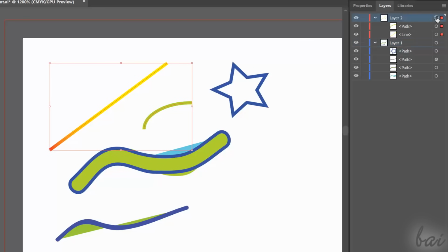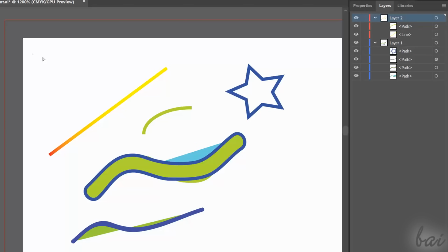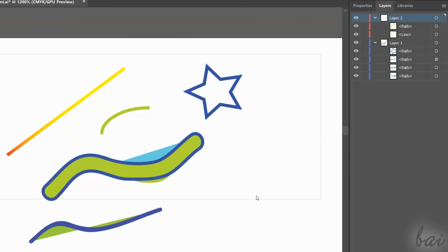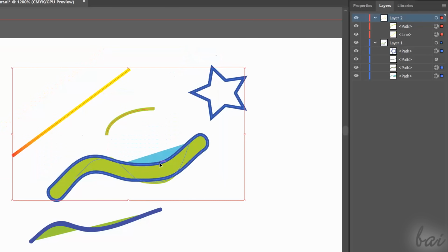You can select a whole layer from the Layers window, or select multiple objects by holding Ctrl down and clicking and dragging to create a selection area. This selects all the objects that touch it. Once all of them are selected, any editing tool is applied on all of them.